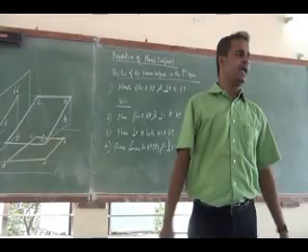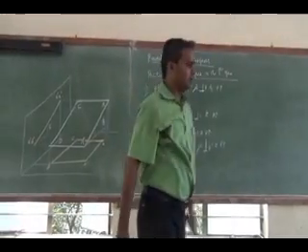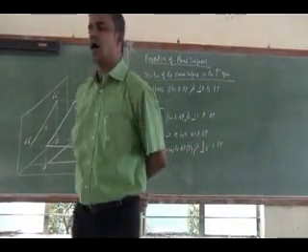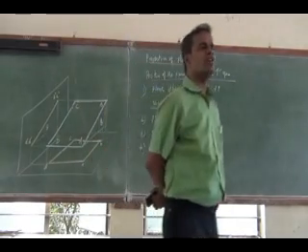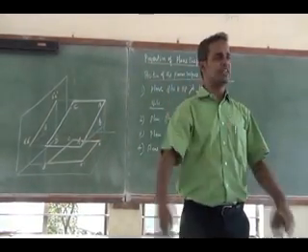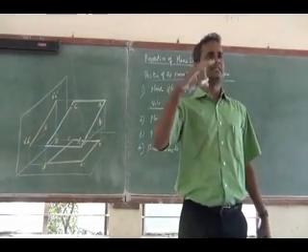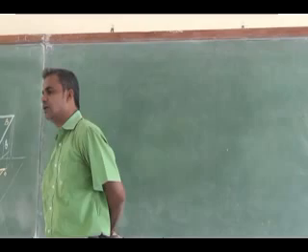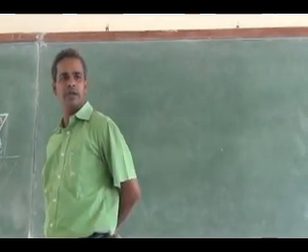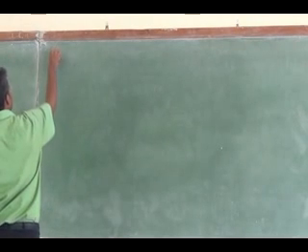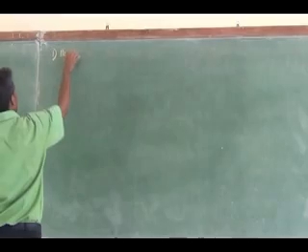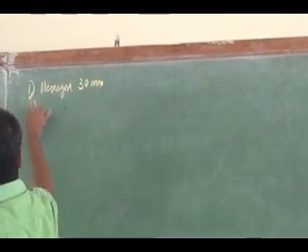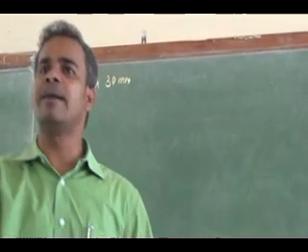A hexagonal plate of side 30 mm is resting on the horizontal plane with one of its edges, such that the surface of the plate is 30-degree inclined to HP. Draw the elevation and plan of the plate. Given data here: the hexagon is of size 30 mm. The second data given is that it is resting with the edge.